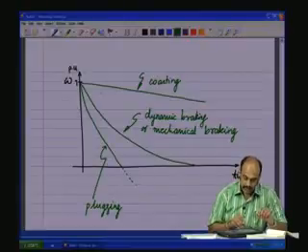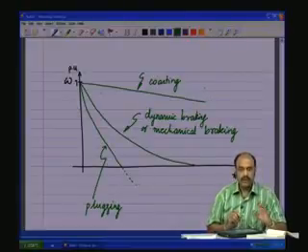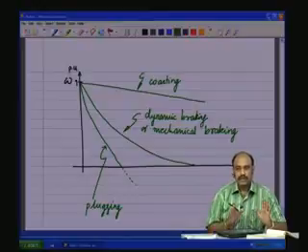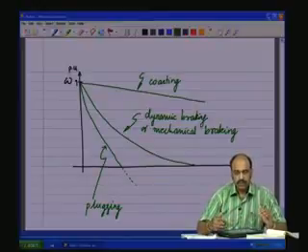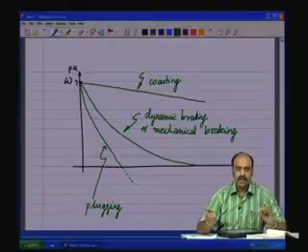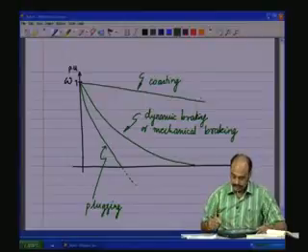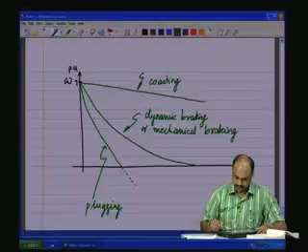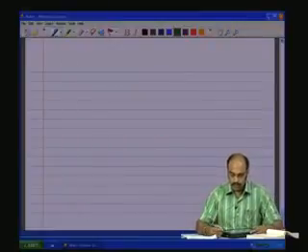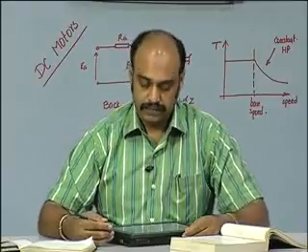And in the case of coasting, it is slowest. There is no control on that, except that it will go to 0 due to the energy which is lost in the bearing friction, windage and things like that. So, that can take quite a long time if the load inertia is very high. So, that is about the braking.